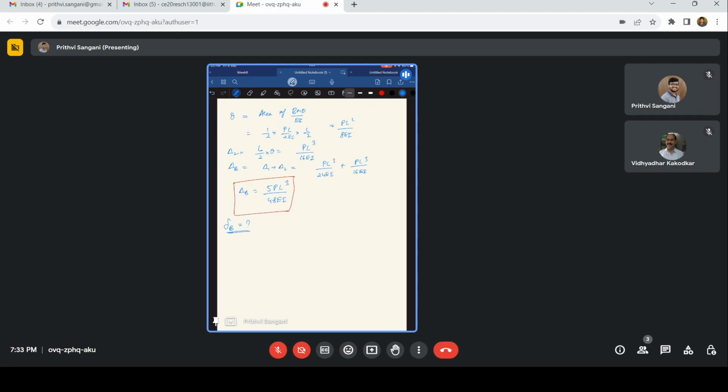What is the compatibility for a cantilever or the fixed support? So the compatibility is that theta A prime plus theta A double prime should be zero. We can also solve in this way. In this method, rather than just taking the vertical force as a redundant force, we can also use this kind of compatibility equation, and in this we'll find M; we'll get the compatibility equation in terms of M. So anyways, I think this is just an introduction, like how we are making use of the compatibility equations to find out